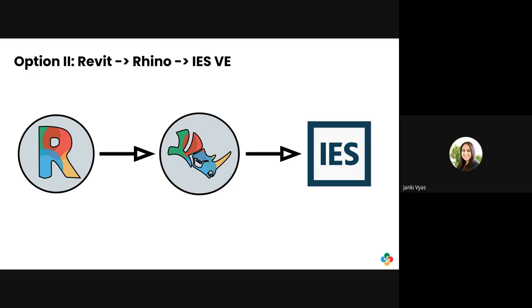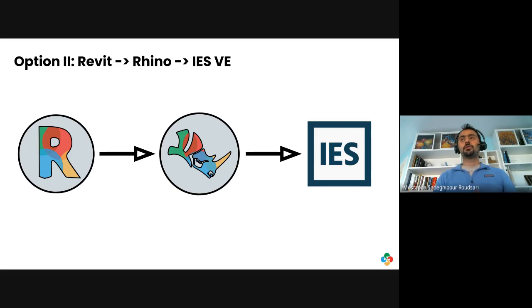Montuan's question: rooms in IESVE that get exported from Revit sometimes have their wall surfaces split based on grid lines, which make the walls choppy. Yes, sometimes. For that one, there are two ways to solve that. If you use solve adjacency, actually in this case, solve adjacency cleans it up. The other way to do that is to go to Rhino, and we have a command PO rebuild rooms. And if you use PO rebuild rooms, it merges all those coplanar faces if you set it to yes.